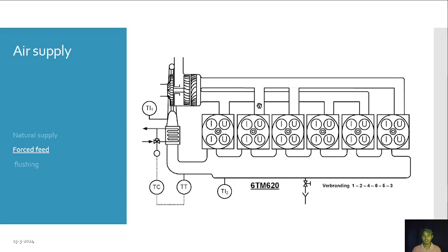So in this type of engine, we have a pulse type exhaust gas system. Pulse type, since there is a narrow tube creating pulsations or high pressure exhaust to our turbine to help it rotate faster.